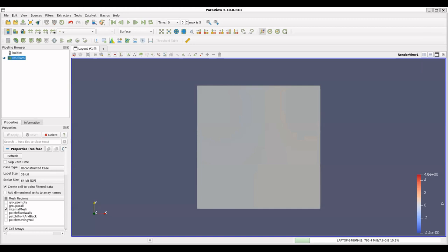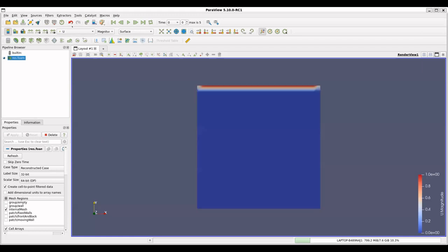So you have 5 time instances, right? And let me see the velocity. Can you now imagine what you have given in the 0 folder initially? The internal field is all 0 value we have given. And in the boundary field, we have given 0 on all these 3 patches, which are fixed surfaces. But this is the only one which is moving.